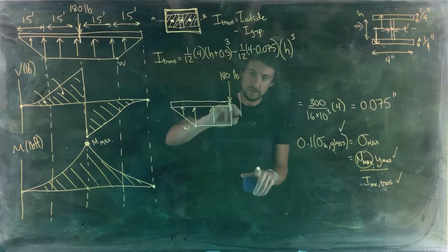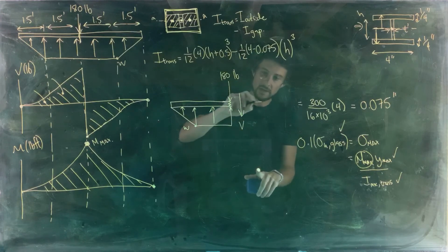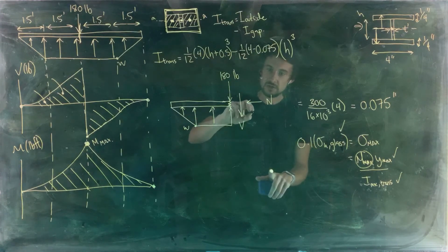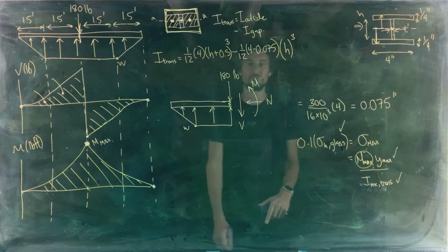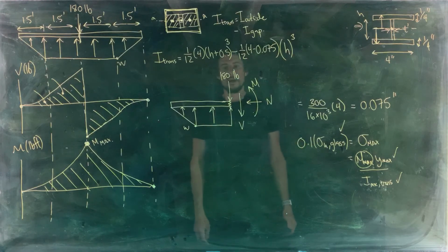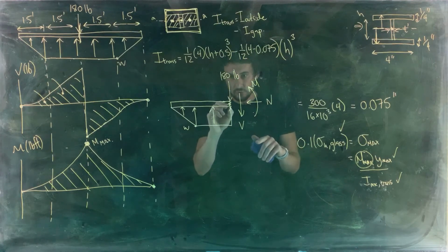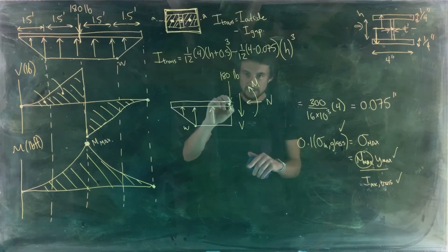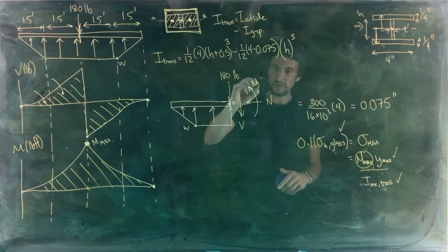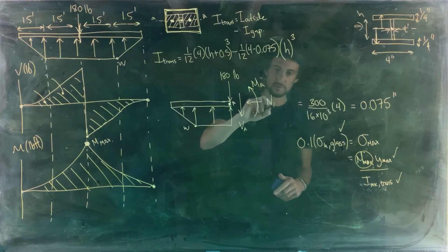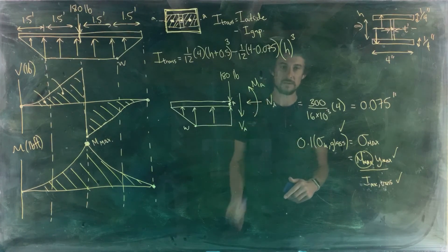So, right, we know we can have an internal shear force V, an internal normal force N, and an internal moment M. Okay, there we go. And this is M acting about the centroid of this cross section, which we'll call point A. So here's M about A, and this would be V subscript A and N subscript A. Okay.